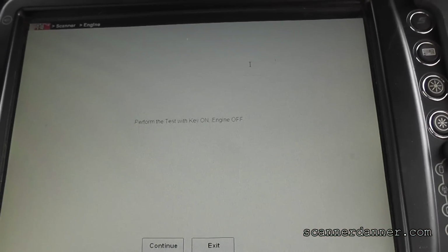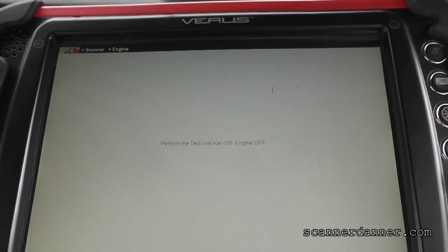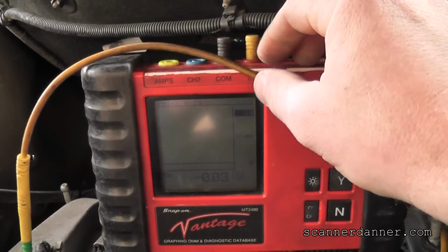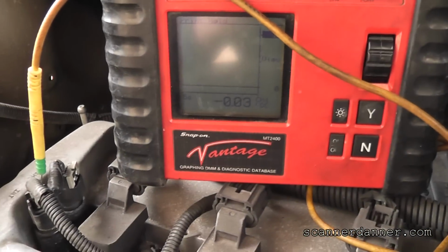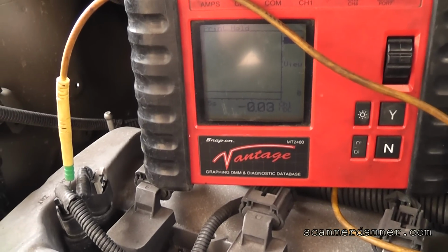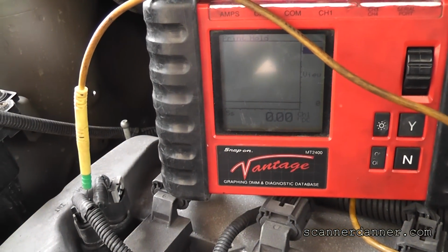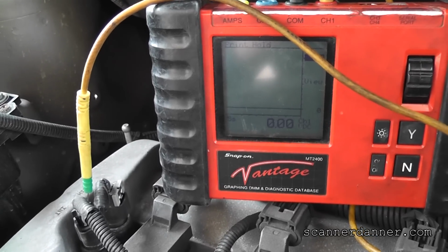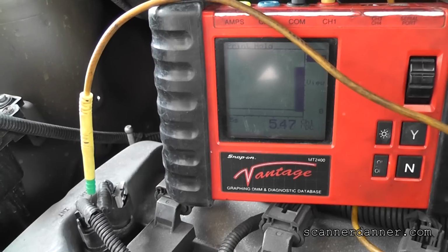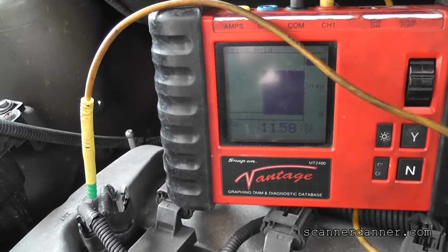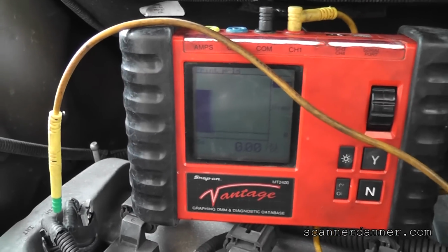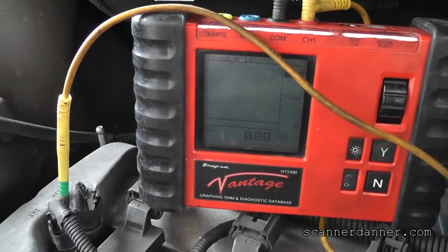All right, so you saw what I was doing here. I'm going to focus you on the meter so you can see the signal, and I'm on the control wire. Remember, the control is power side switched, and it's pulse width modulated. So what we're going to see is an up-down signal on here. It's all we're looking for. There it is, right there. Turn it on, turn it off. That's good. That timed out again very fast.